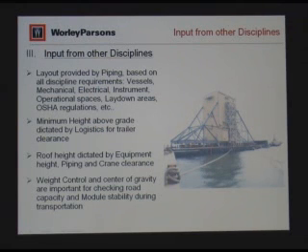Lay down areas, OSHA regulations, all this, they take them, they put them together, and they are the architect of a module. So for instance, this module is decided to be very high, because there are some vessels inside, and the operation is such that they need to be on top of each other. Now, the module is dictated, therefore, by piping, and the minimum height above grade